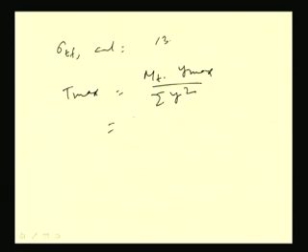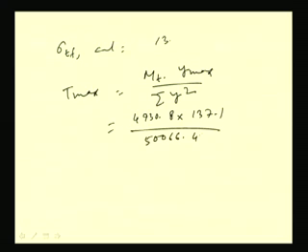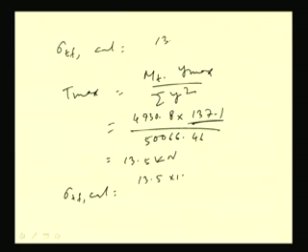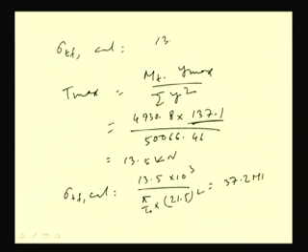So that will be 4930.8 into 137.1 by 50066.46, because Y max is this outermost. So from this I am getting 13.5 kilonewton. Now sigma TF cal can be found out: 13.5 by area, P by A, pi by 4 into 21.5 square. So this is coming 37.2 MPa, which is less than sigma TF, which is 100.